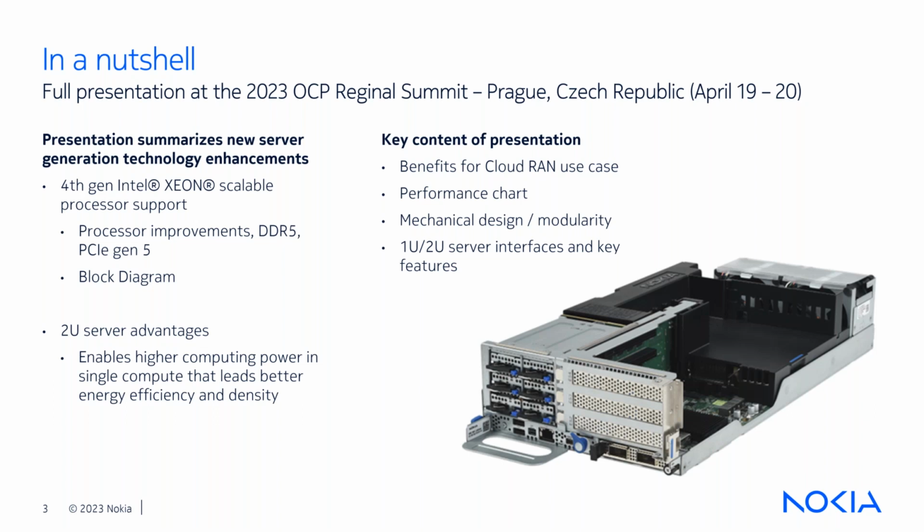It can be GPU cards, or it can be Cloud Run SmartNIC-like accelerators, which are crucial in cloudified vDU designs, but basically any add-on card having significant high power, because we continue to have very efficient cooling in the system, so we can cool a 300 watt full height, full length, double width card, or we can cool 3 times 75 watt or even higher half length cards in this design.